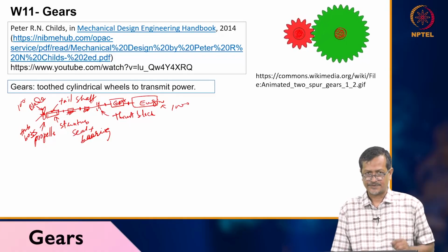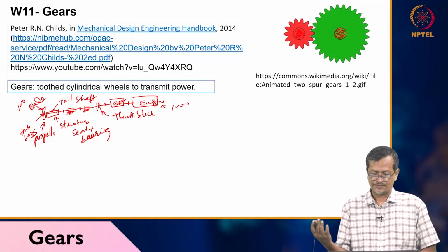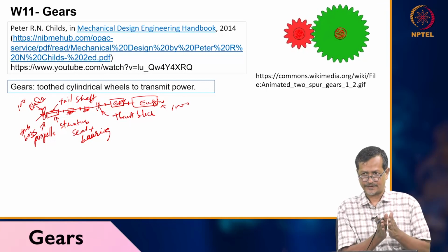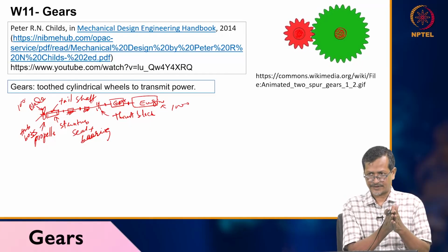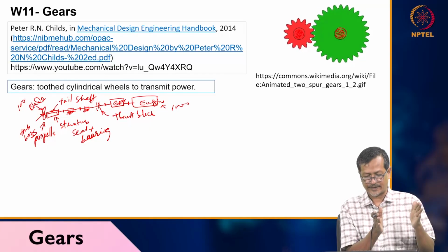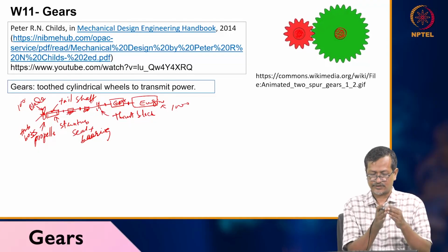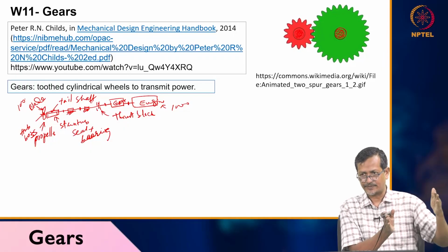And engine speed can be 1000, 2000, 3000 rpm also possible. So based on your engine speed, you have to select your gear or gearbox, then reduce the speed. Then it will be transferring power to the shaft. The shaft will be connected to a thrust block. The thrust block will be taking all the axial loads. Then it will be passing through several bearings. There will be intermediate shaft. Then it will go to the tail shaft. So the tail shaft will be connected to your propeller.